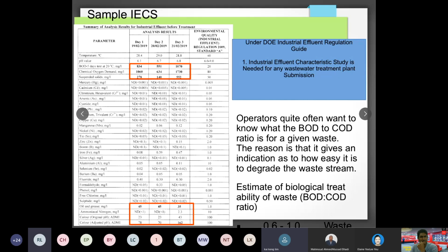I'll take wastewater as an example. We have physical-chemical treatment, where we talk about the dosage of each chemical, for example coagulant and flocculant, and after that you go to a clarifier or settling system. The settling system is the area where we apply our chemical engineering knowledge about surface loading, retention, and whether it's undersized and that sort of thing. So when I joined the water treatment company, I was helping customers make sure the wastewater treatment system operates at optimum.